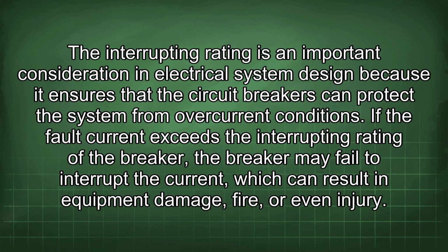The interrupting rating is an important consideration in electrical system design because it ensures that the circuit breakers can protect the system from overcurrent conditions. If the fault current exceeds the interrupting rating, the breaker may fail to interrupt the current, which can result in equipment damage, fire, or even injury.